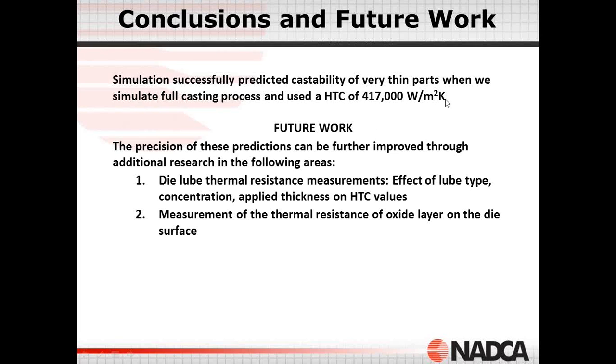Just a word of caution for those of you who would be interested in trying this: this is the moment liquid metal touches the surface. The minute the material changes phase into a solid, the heat transfer coefficient at the interface will dramatically decrease to the order of about 2,000, and that's based on measurements that we have looked at as well.